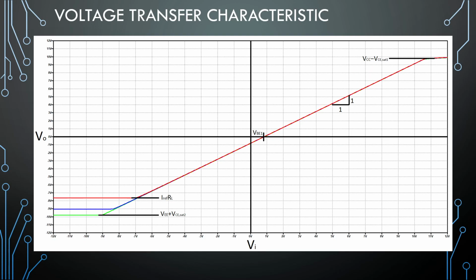Right, so a voltage transfer characteristic. So for any input voltage, we have a given output voltage. We will saturate our amplifier near the rails. Now what you'll notice is we do not get right onto the rail like we should. But we should remember that transistors have saturation voltages, and this is typically at 0.3 volts.